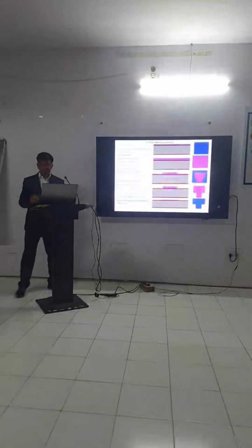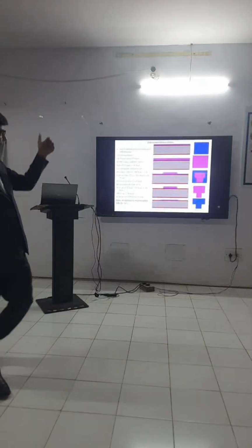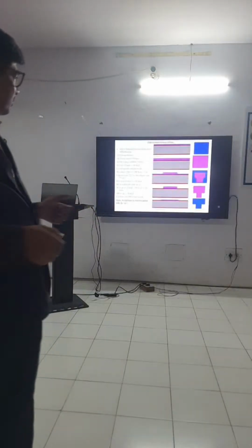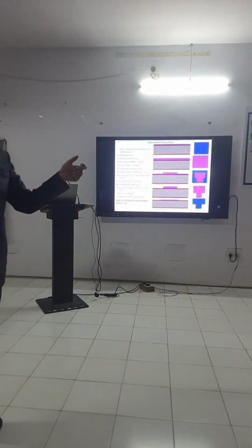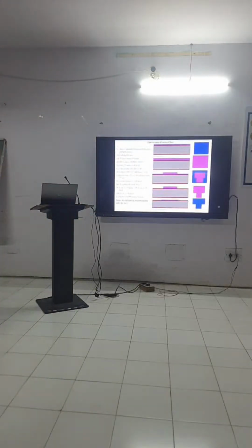This step is the same you have to follow for designing your heater. Here we are patterning my top electrode over the oxide layer. Similarly, we are patterning my heater over the oxide layer.